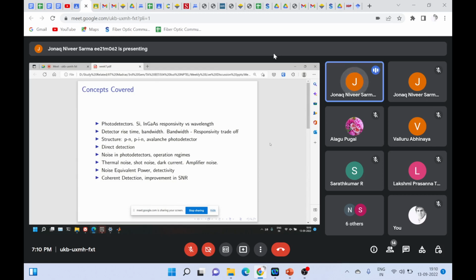during this week we kept considering a constant signal power in most cases. So even though we are talking about this on-off-keying kind of cases, when we're talking about SNR and all these things, we're talking about only when power is on or off, like we are not averaging over each sequence. I think ma'am touched on it in class also.